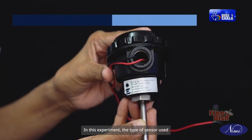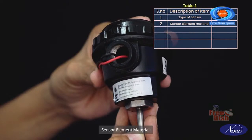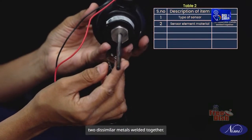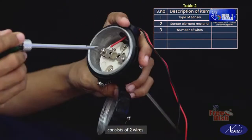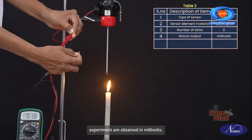In this experiment, the type of sensor used for temperature measurement is type J. Sensor element material. The sensor element material utilized in this experiment is composed of two dissimilar metals welded together. Number of wires. The sensor configuration consists of 2 wires. Sensor output. Temperature readings in this experiment are obtained in millivolts.